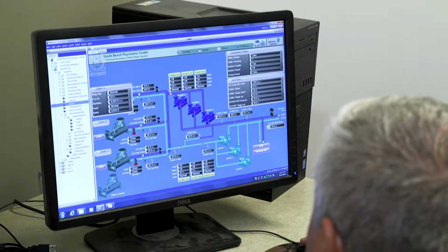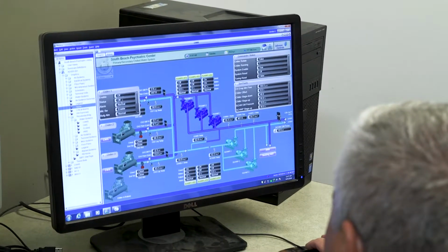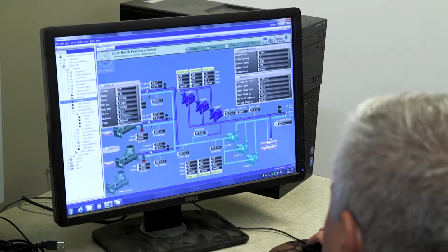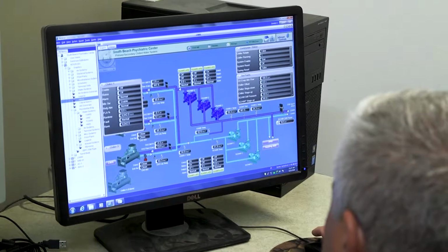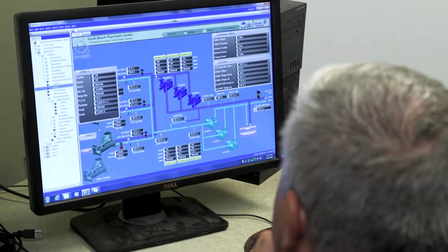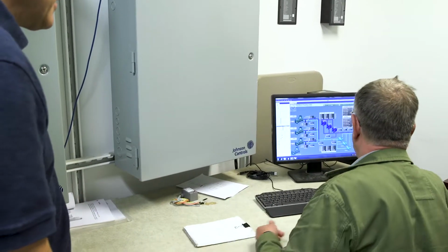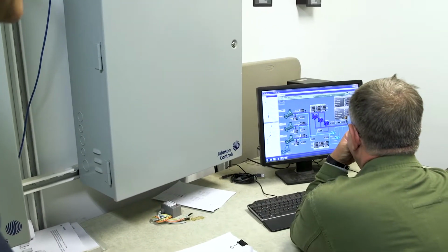No, you don't have to scroll down. You can open it up, make it bigger. Yeah, you could expand it. Go down to the bottom line. Press there. Now drag that down. Yep. Now all your information on the chiller is there, so you just watch the full load amps start going up as the chiller loads. Can you open up the VFD and tell me if you have any individual points on the VFD?